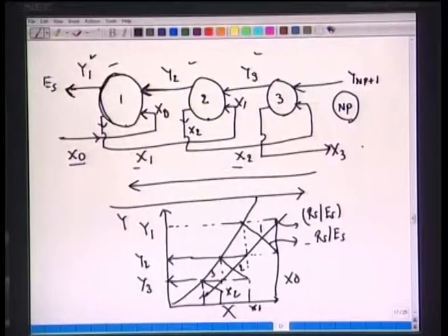In other words, there are two ways of representing this counter current overall process. For counter current, we can have this operating curve with slope Rs by Es. If you look at stages 1, 2 and 3 individually, it is possible to draw the lines with slope minus Rs over Es individually for a co-current process to achieve the same results. So, we have taken two different scenarios: one is a cross co-current and another is counter current stages. We can assume that if these stages are ideal equilibrium or theoretical stages, then the two leaving streams are in equilibrium.